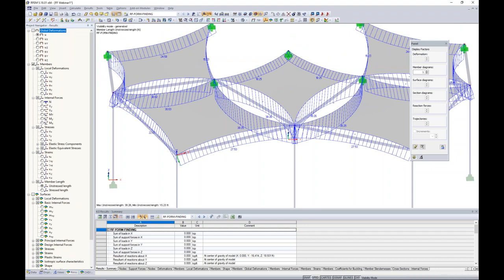We also give to you the unstressed length. I think that this is really important because this is information we want to give to our manufacturer to ensure that they manufacture these cables at the correct length, which would probably be this unstressed length, so that by the time we get out in the field and we apply these pre-stresses, then we should achieve this stressed length here. So both are given to us.